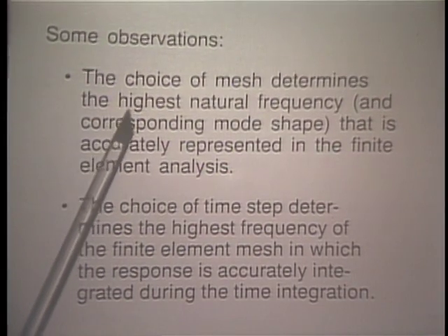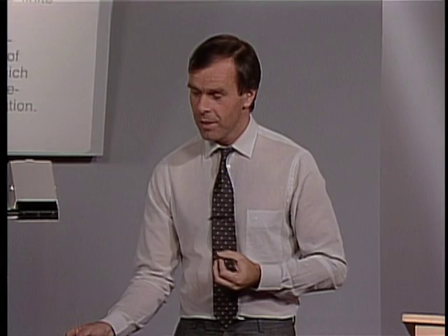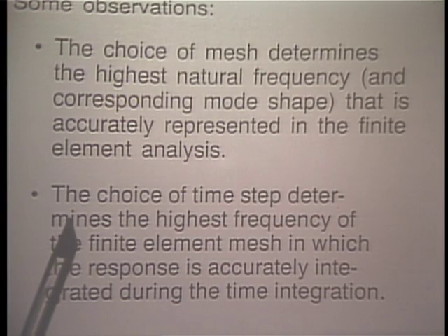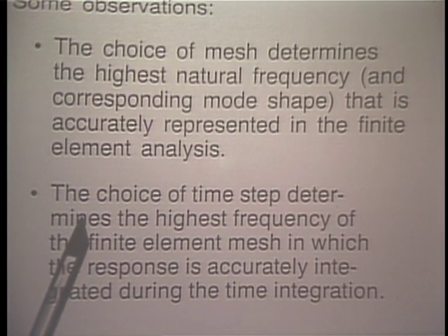Let's look at some observations. The point is that the choice of mesh will determine the highest natural frequency and, of course, the corresponding mode shape that is properly, accurately represented in the finite element analysis. The more elements you use, just as a rule of thumb, the higher the frequency that can be properly represented, that can be accurately picked up with the choice of mesh you're using. The time step that you're using will of course determine how high a frequency you are integrating accurately.